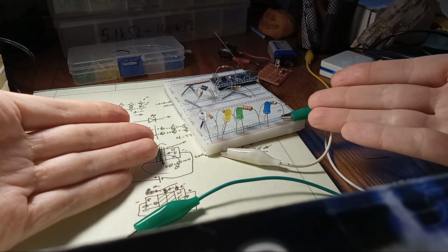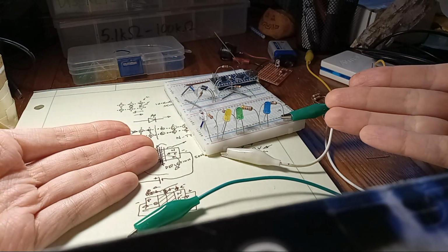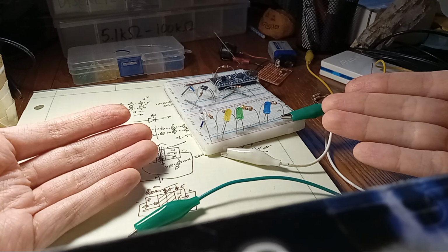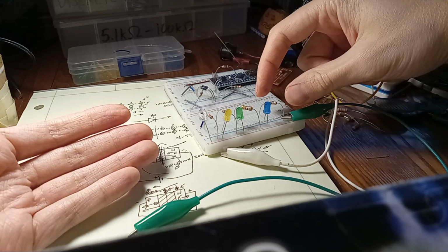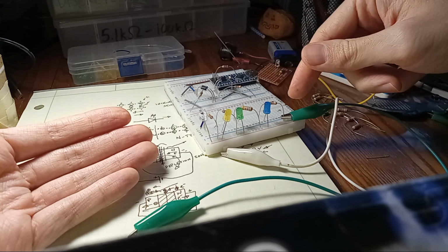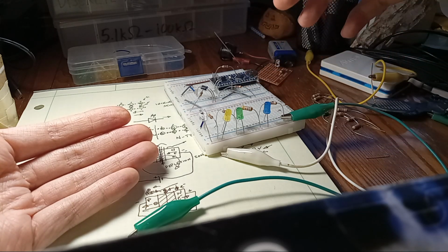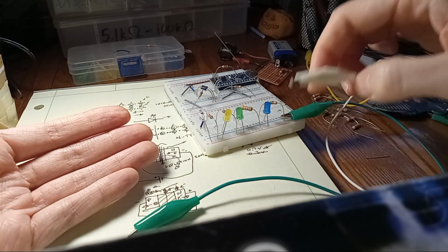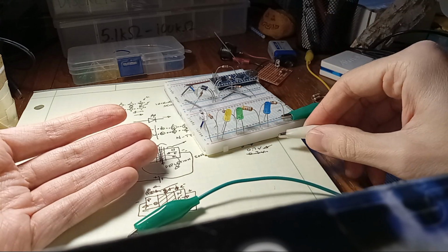The LEDs all have identical 1 kilo-ohm current limiting resistors. In practice, their difference in voltage drops will mean that the resistors have slightly different voltages across them. Therefore, because of Ohm's law, they'll conduct slightly different currents. But this should be a second-order effect whose size is relatively minimal, so we can safely ignore it for now.